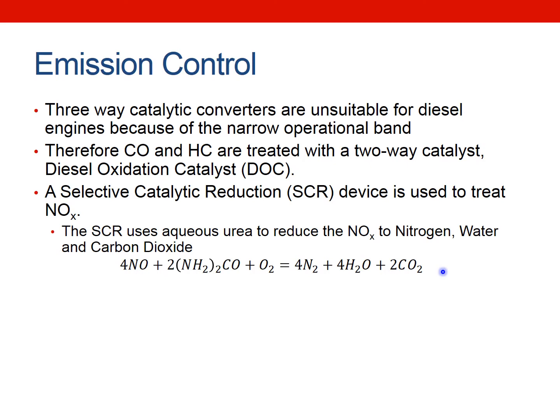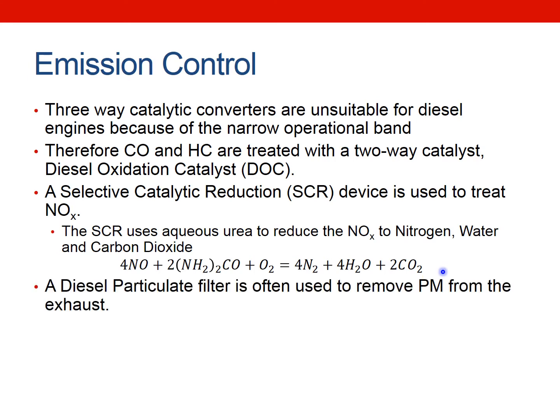As I say, this is actually sprayed into the exhaust, and you might have seen some of the diesels on the road, or AdBlue at the pumps. AdBlue is just a trade name for the commercially available aqueous urea solution. So it's a separate tank that's actually carried with the vehicle and sprayed into the exhaust.